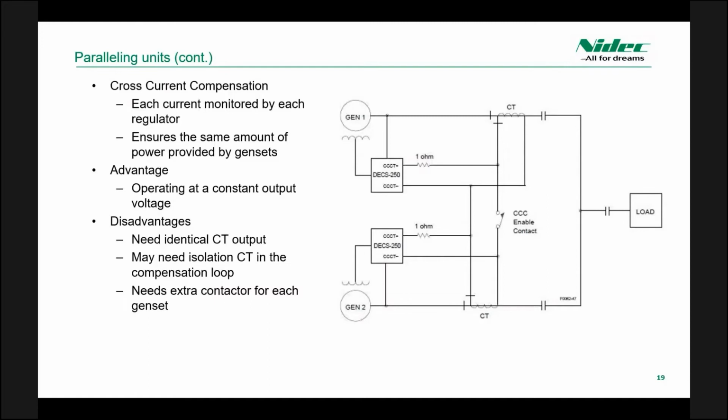The disadvantages include extra wiring that can get complicated. Also, the CTs need to be identical, or further calculation will need to be done to ensure that the current seen by other generators is compensated for. Lastly, the generators will need extra contacts inserted at the CTs so that the CT can be bypassed if the user wants to only use one of the generators at a time.